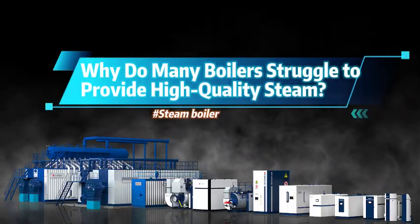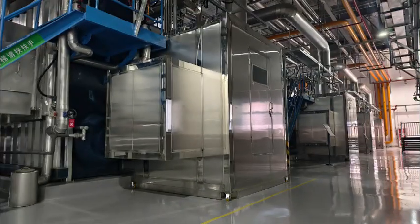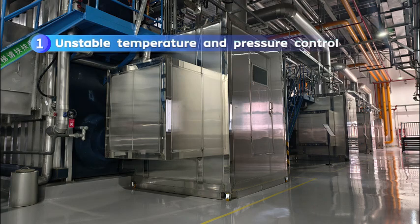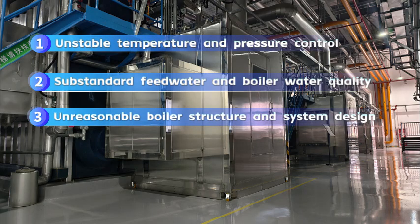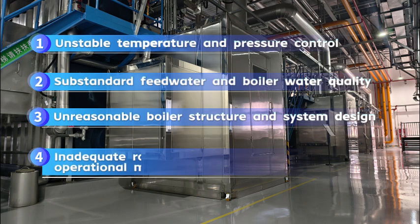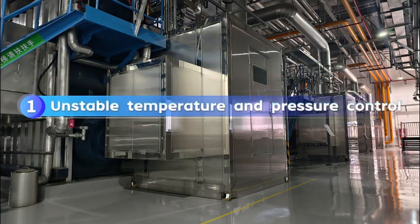Steam boiler. Why do many boilers struggle to provide high-quality steam? 1. Unstable temperature and pressure control. 2. Substandard feedwater and boiler water quality. 3. Unreasonable boiler structure and system design. 4. Inadequate routine maintenance and operational management.